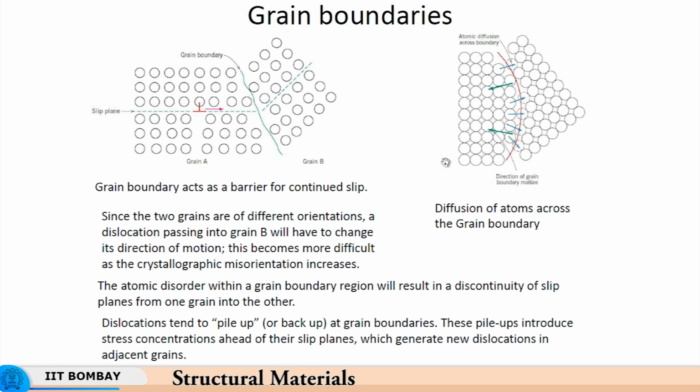Now these grain boundaries therefore act as regions of high energy because you have a number of defects concentrated here. The atoms are not located at their minimum energy positions, and that is because the grain boundary is a highly disordered area, whereas a grain has an ordered structure, an ordered layout of atoms. Yes, there are defects which disrupt this orderly arrangement.